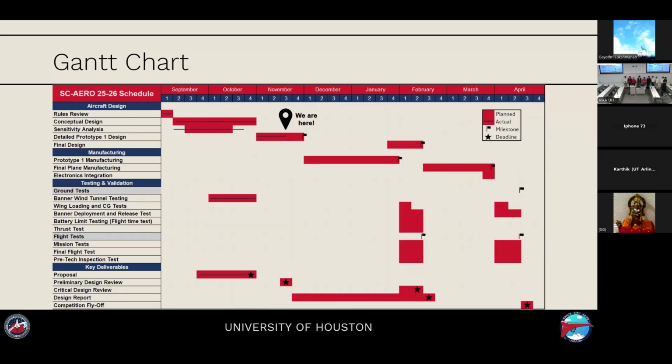For the wing, there's that main spar and then there's the carbon rod. Just keep in mind that the carbon rod is probably only going to be good for keeping the spar or the ribs in place, but it's not going to be good at preventing the wing from twisting. And 4 feet is still long enough that the wing might start twisting. So just be mindful that you might have to have a secondary, like a rectangular spar, that goes across if needed.